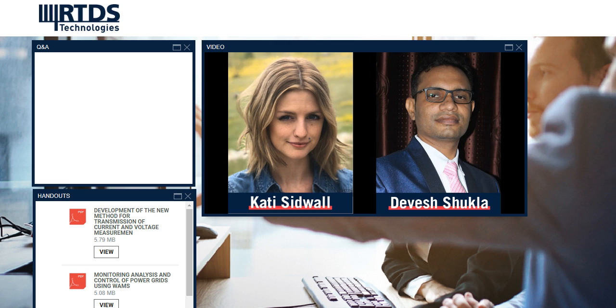We are working on that, developing bad data detection or some event detection kind of thing. We are developing a mechanism using information theory where the data streams would be quantized and analyzed, and a span over which the data would be archived for post-processing or analysis is under development. We are using a transitional probability matrix and transitional window matrix for doing that. That is the work we are currently doing in that field.